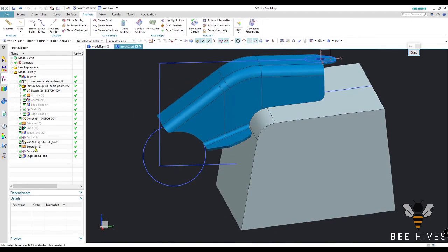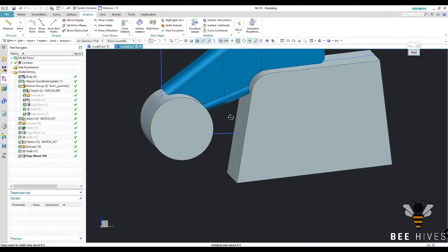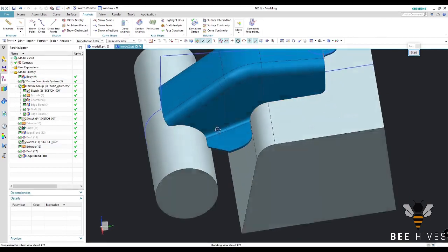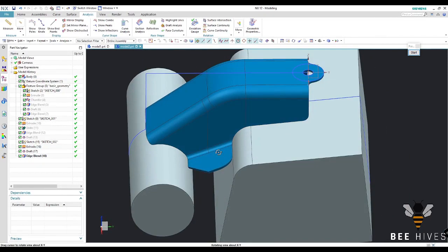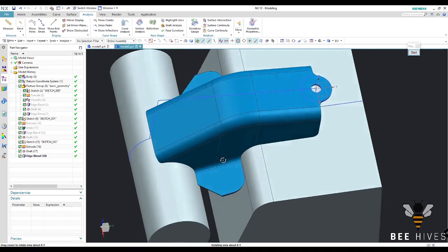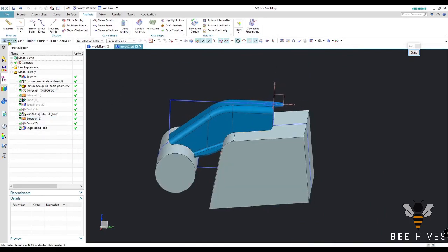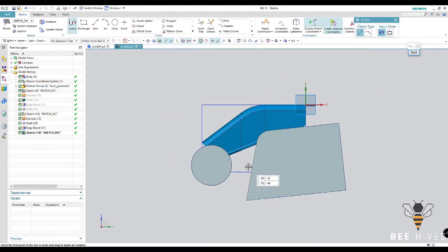So these are the things. We have two extrudes, a draft, and a fillet as given, and it's completely matching at the end. Now we want to go with the welding flange. This welding flange can be done with even a line, we do not need any rectangle for that. Always remember to give proper feature groups so that the parametric model is editable and foolproof.